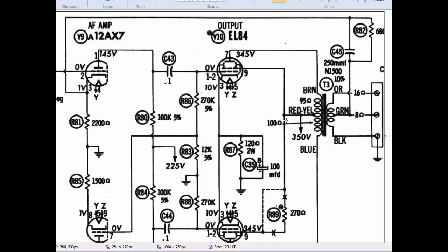Well, if you'll start noticing, right there's one of those source places that it feeds to. The 350 volt source connects right here. The 225 volt source connects right here. So those source points in the other part of the power supply feed to this part of the amplifier to create the right operating environments for these tubes to operate properly.